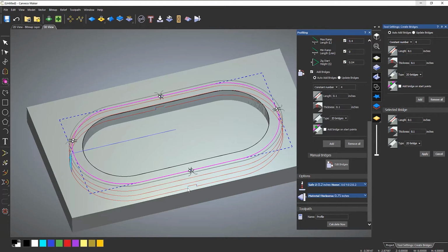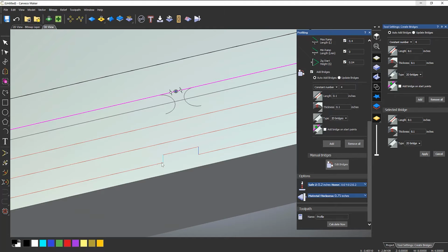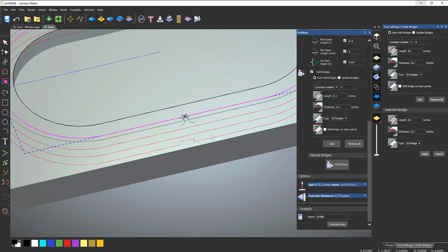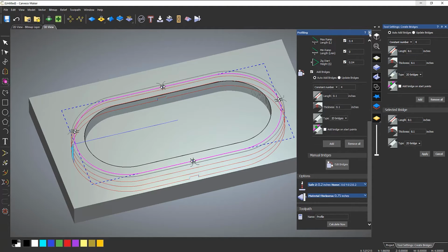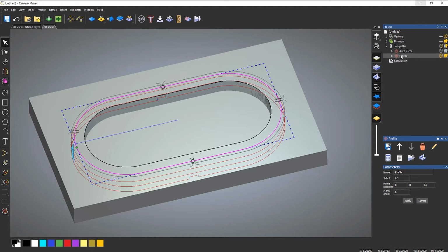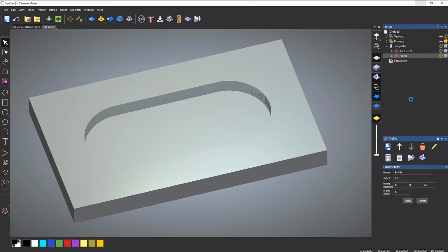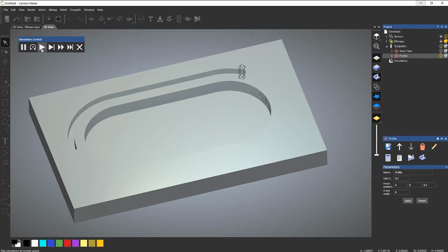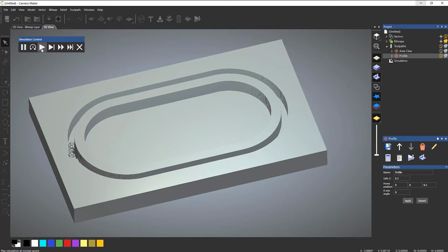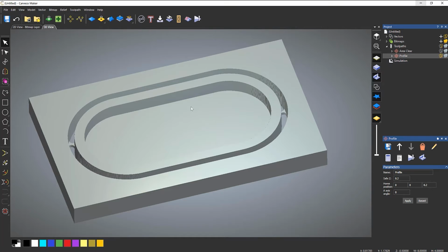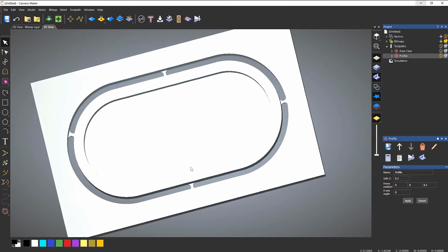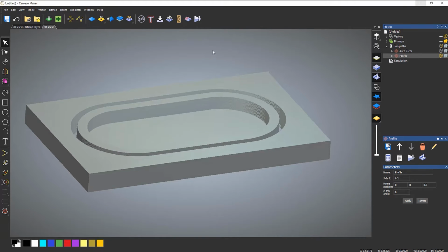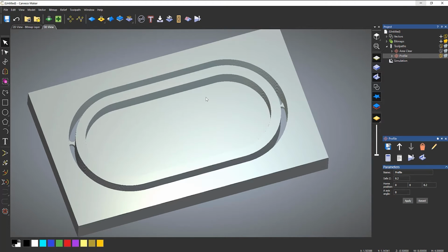and you can see here this is where the toolpath comes along and then jumps up and comes back down for the tab. So if I close that, and then let's simulate that one as well, press play, and you can see that it's cut the part out and it's left those tabs in there so the part doesn't move. So that's a really basic tray.